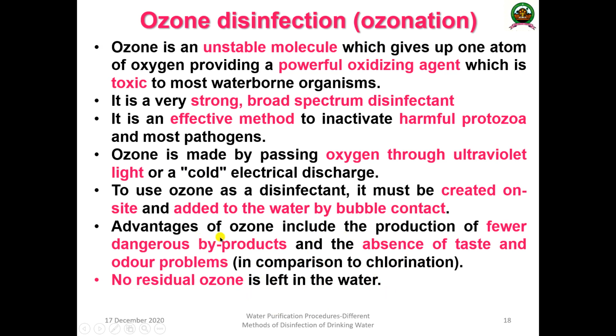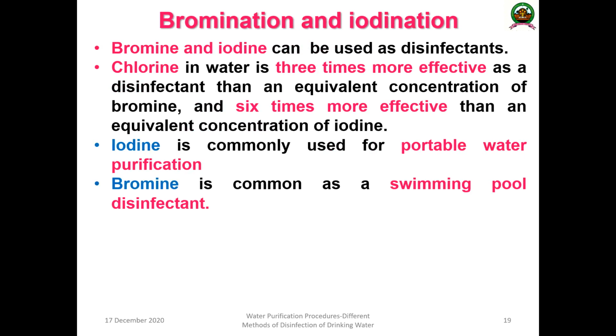The main advantage is that there are fewer dangerous byproducts, and there is no problem in the taste or odor. The original taste or odor will be retained, which was the major problem. In chlorinated water, there will be a taste difference and odor difference, but there will not be any residual ozone left in the water.